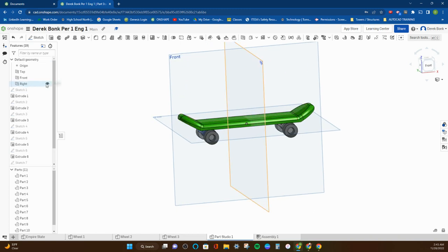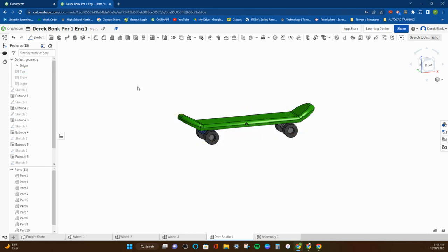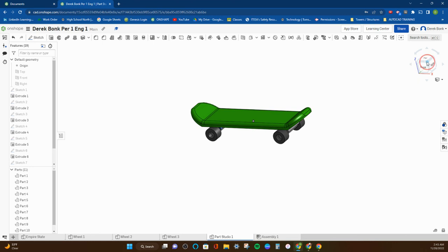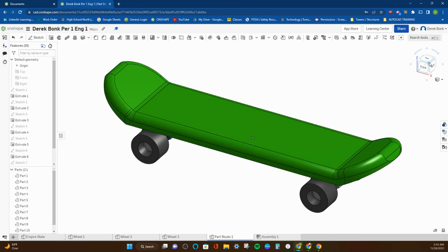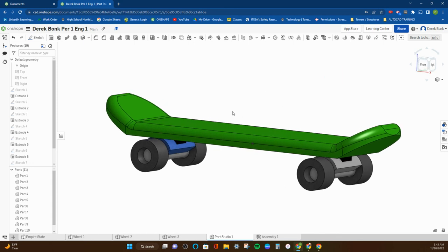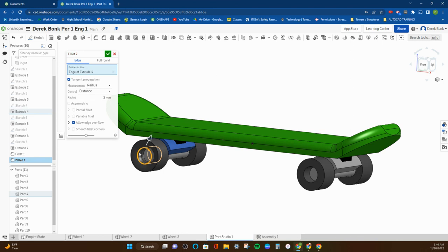And then I can go up here, turn the visibility of my drawing surfaces or planes off. Another thing, default view, just click this corner of the cube. When you're looking at top, look at the bottom right corner. I click that, that brings you back to your default view. Zooms in nice when you turn the visibility of all the planes off. And that's like super quick tech. I mean, there's all sorts of other mods, actually, little things.